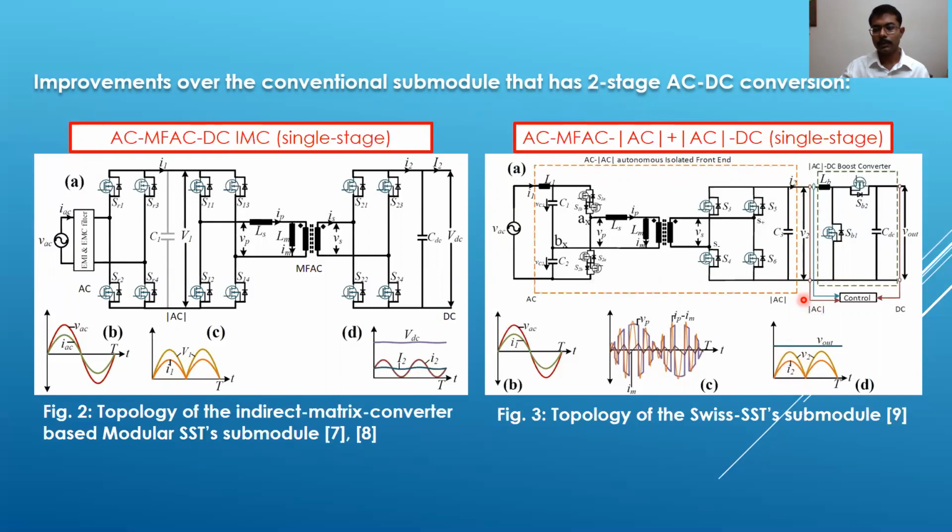So you can see here that it has a similar kind of advantage, where the ripple is being transferred from having a stiff second harmonic filter to the DC side, so that the interleaved operation could cancel the second harmonic ripple, and you're left with only the switching frequency ripple. Here there is an additional improvement where the number of switches is lower. Compared to the 12 here, you'll have only 10 here.